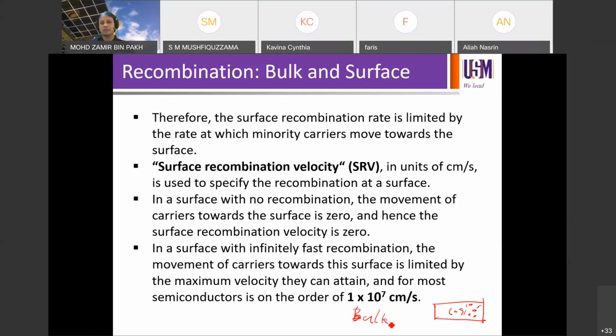On the other hand, if you talk about surface recombination, we are talking about recombination that happens right on the surface of the device or on the semiconductor. So that means it can happen here, can also happen here. At the edges it is less, because it's usually very thin, but this one is quite big. If you're operating like the wafer that I showed to you last time, 6 inch by 6 inch, the whole surface of 6 by 6 inch squared may have surface recombination, front side or rear side.